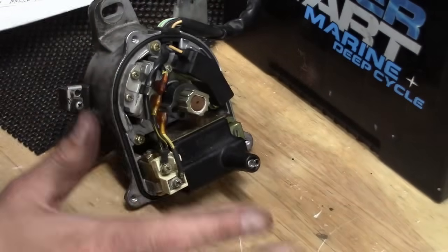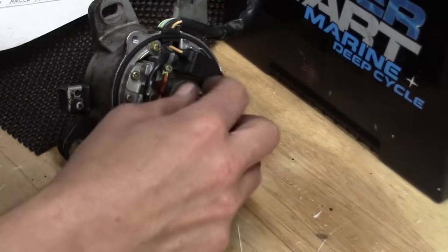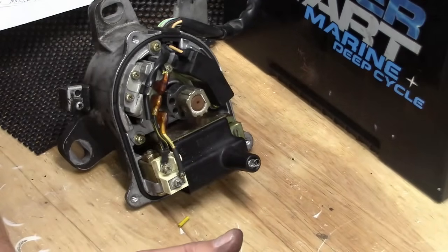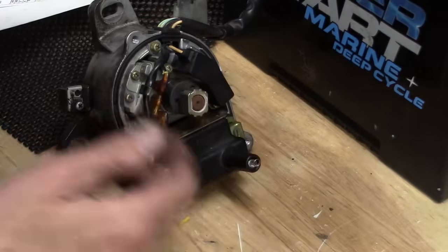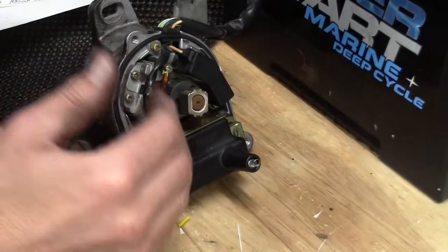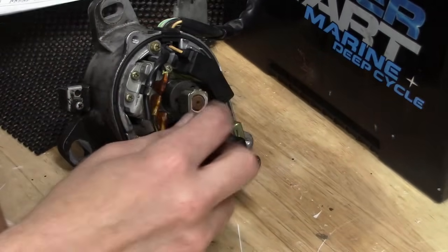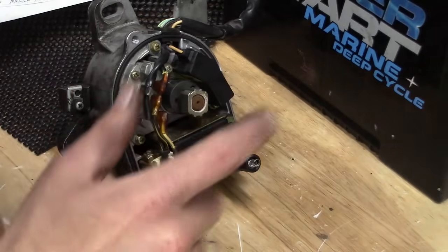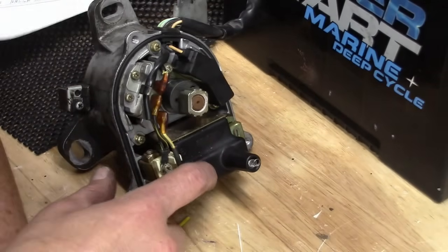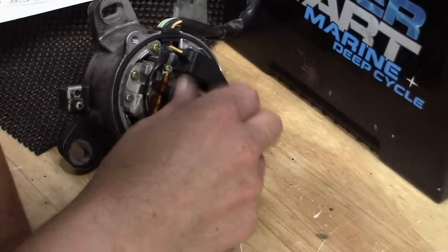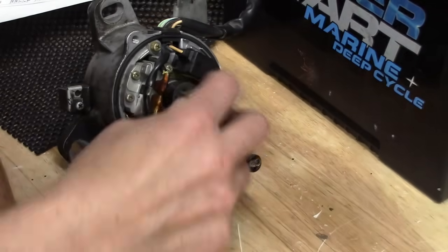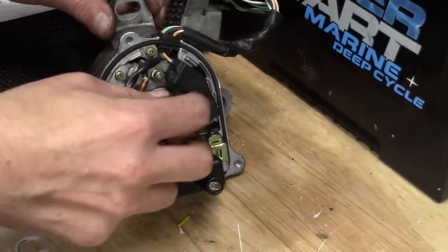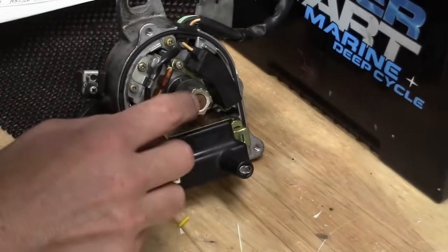Boy, honestly, this distributor needs to be replaced anyway, but I'm not just going to call an easy out on this and go, well, the distributor needs to be replaced anyway. No, we're still going to figure out exactly what the issue was, because remember, this car also has a compression problem. So if I can get by just replacing the coil, that is what we are going to do. So let's see here. As you can see, we've got a reluctor here. We've got our inductive sensor, so that is going to be the crank sensor.